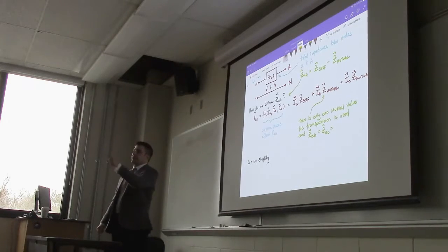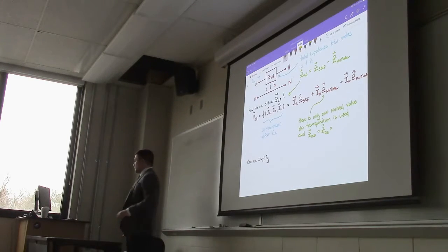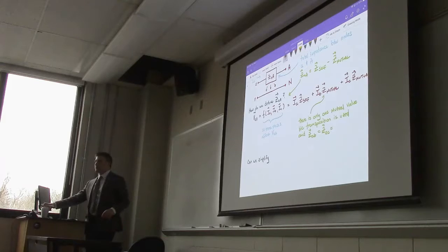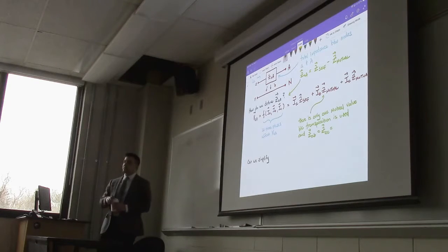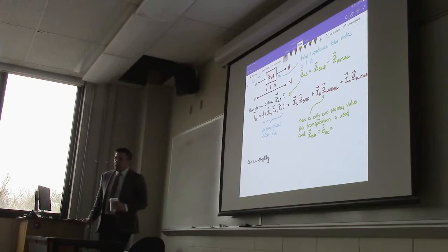Yeah. Okay, good. Is that why when they use the big metal power lines, they space them out pretty far, because they're sending so much current through it that they want to reduce the impedance from the other lines? That's part of it. The main part is they use probably the minimal spacing that's required to prevent a flashover.